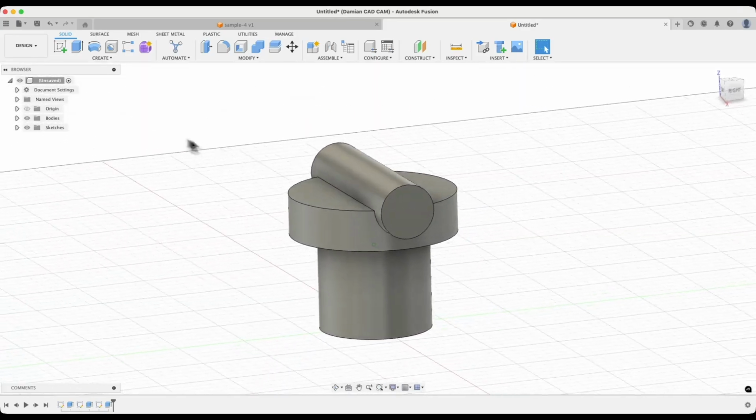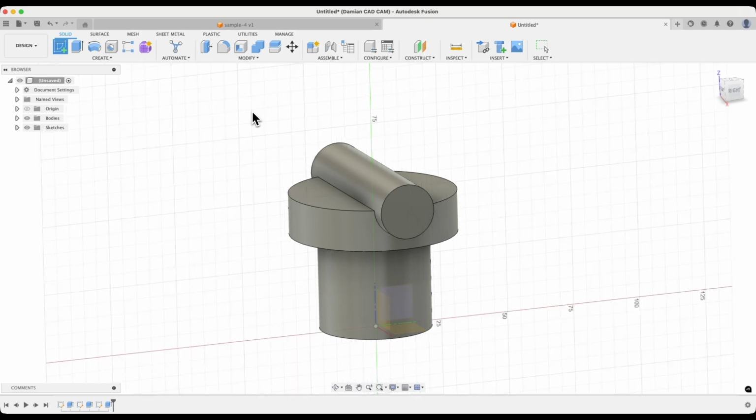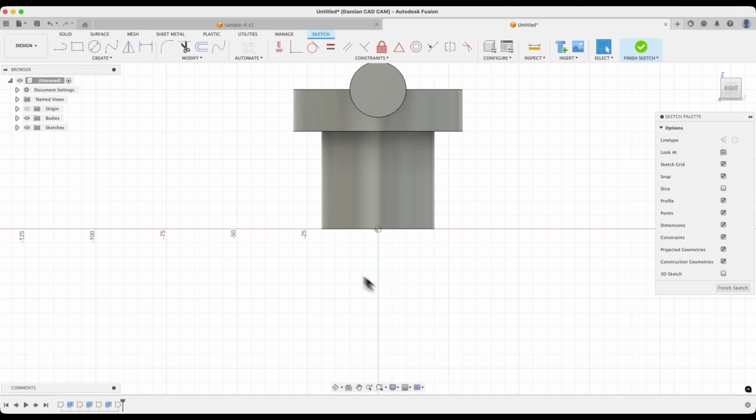Next, we will create another sketch. Choose Sketch Creation and select the XZ plane as the sketch plane. This is the plane. We click on this plane and now select Line Drawing. Draw a line roughly like this, so that the first point of the line is here and the second point in here, and create this shape roughly like this.